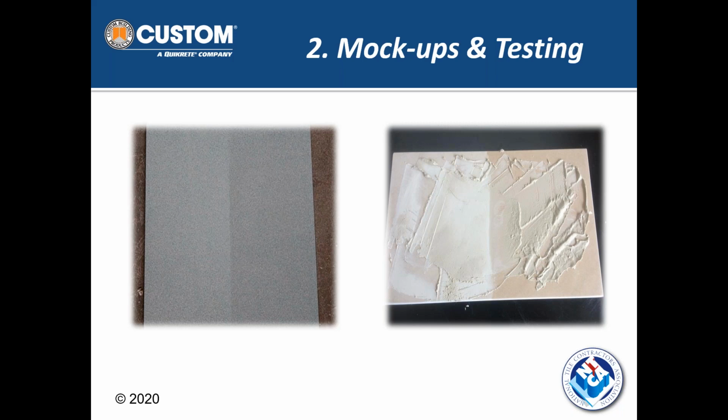Notice on the right, by the way, I took this picture within minutes after putting grout on the face. Notice on the left side, it's getting lighter. Why, Bill? Because the moisture is being pulled out of the grout right into the stone. So it's setting up quicker. And that's not a good thing, right? It's not a good thing from a variety of standpoints, but in terms of working time, one of the complaints I always hear is, wow, I just don't have as much working time as I would like with this material.